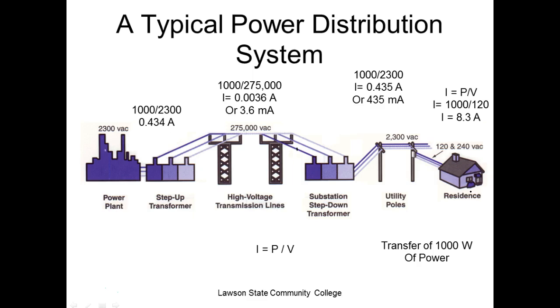But if I took my air conditioner and tried to run it off 120, it's probably not going to even run. If I tried to take something designed around 120 and run it on 240, it's going to burn up as soon as I plug it in. So your loads are designed around a certain voltage, and you need to run them on that voltage. So 240 means smaller conductors.